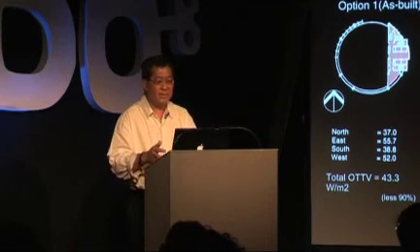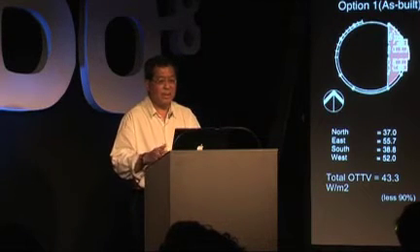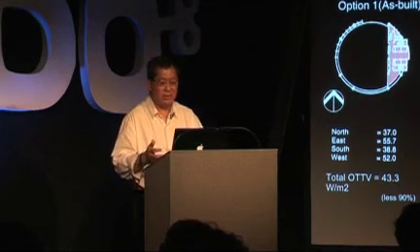Now, as an index, what it means that this diagram informs us is that if you start with the right shaping of the building, the right orientation, you start with a low energy building before you put anything else in. Then anything else you put in can only further enhance its energy performance. But if you don't, then you probably have to have additional heating systems and cooling systems, which then makes total nonsense of designing a larger building.